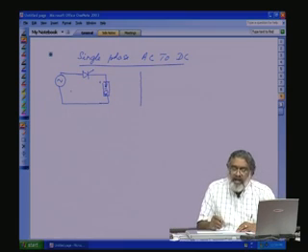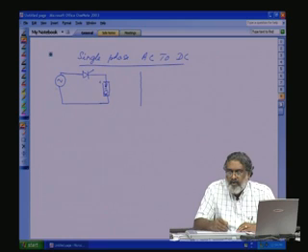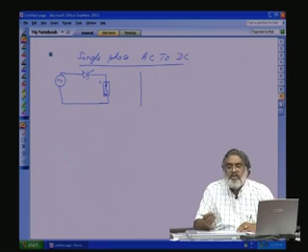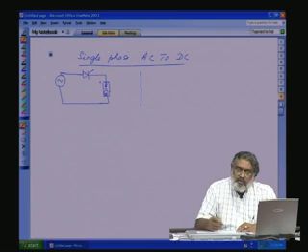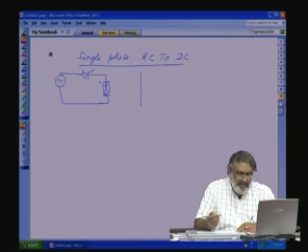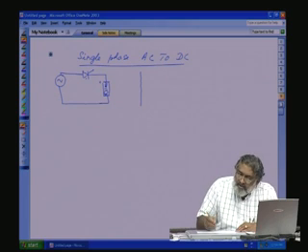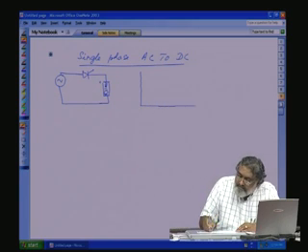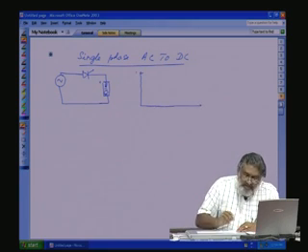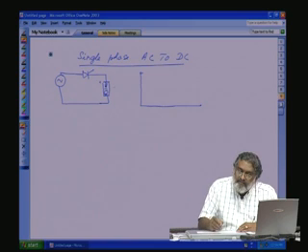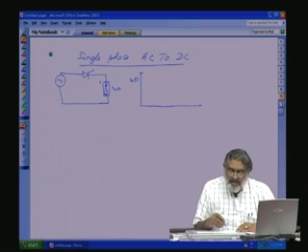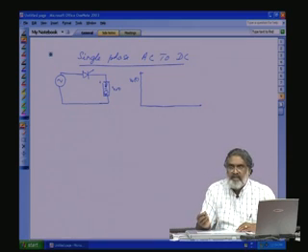So, at the appropriate point of the mains, we will be turning on the device and we will be transferring the voltage to the load. So, by controlling the firing angle of the thyristor, we can control the output voltage. How can it be controlled? Let us see. This is our V0. What is the nature of V0 for a single phase with a single thyristor controller?